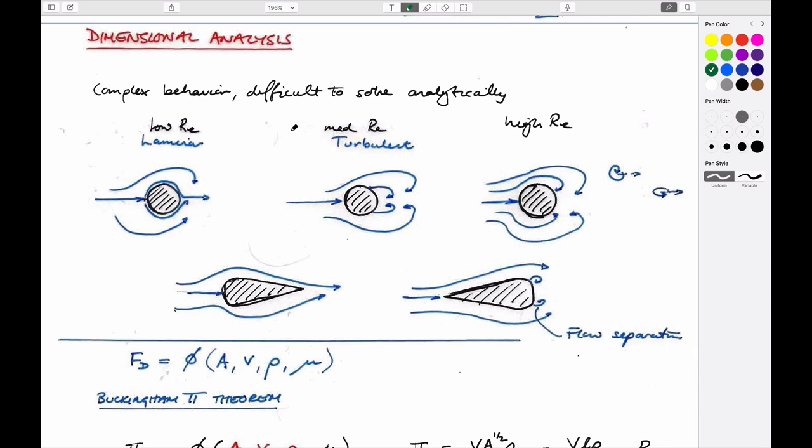So it comes back to wanting, if we're doing model studies, to have the geometry right and the kinematics correct. It's epitomized here: as you increase the velocity from a low Reynolds number to a higher and an even higher Reynolds number, the geometry of the flow changes. Therefore you have to do your experiments or create your models at the right Reynolds number, and only then can you use that to calculate the right forces on the system.